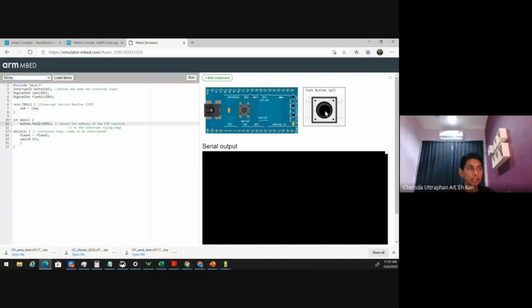Again, I press already, I haven't released yet, so it will still be the same. I press, I release, and when I release, it will be off. Press, not yet. Release, it will be on. Press, not yet. Release, it will be off. So that means it is detected at the falling edge of the input. All right, so that is the flexibility that you can use.